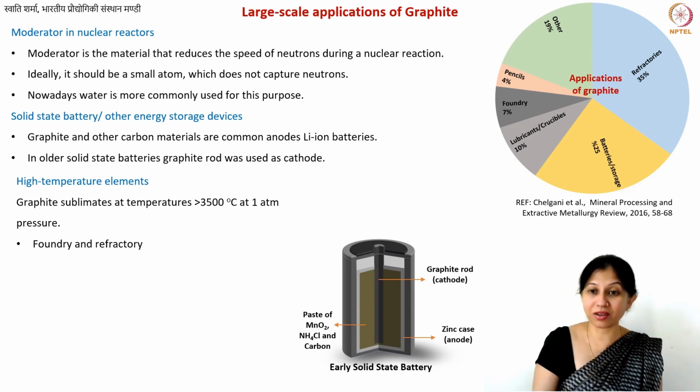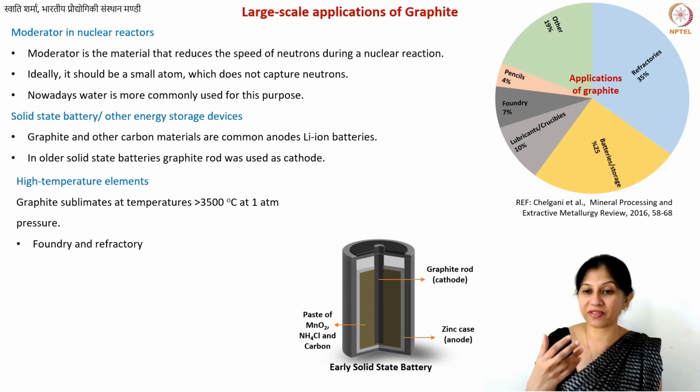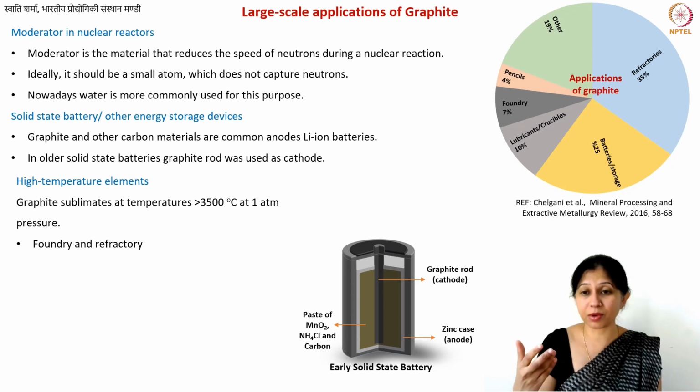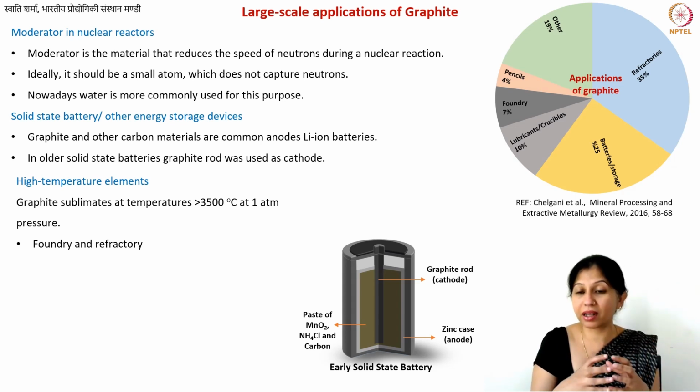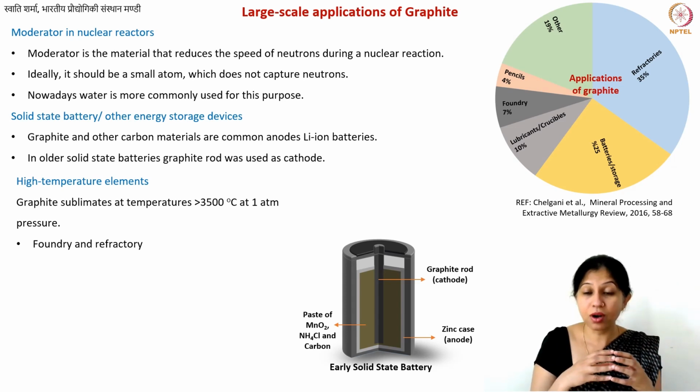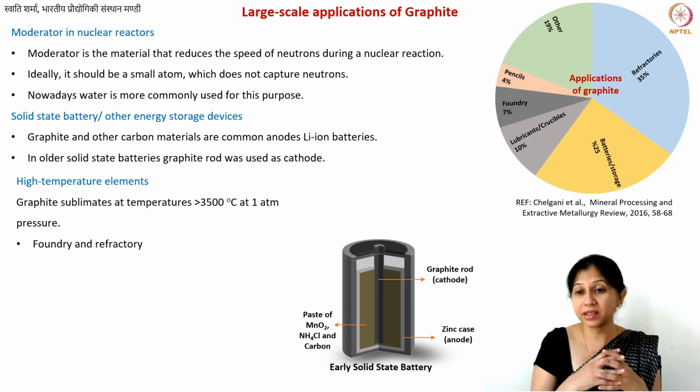The sample holder also should withstand that temperature, not just once, but it has to withstand that temperature every day, multiple times. So it will also have thermal fatigue over time. It will definitely have here and there thermal shocks. So all kinds of high temperature conditions, the sample holder and all the other parts of that furnace need to withstand.